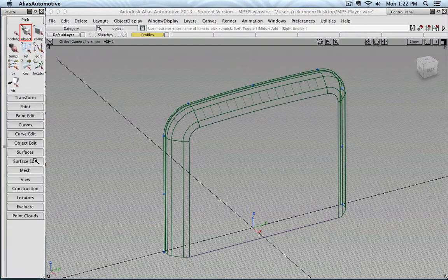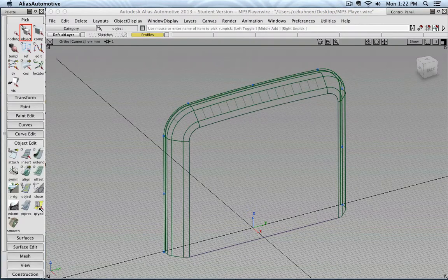And of course, again, if you would like to change those values later, you can always go to the query edit, click on the fillet, and then it jumps back to the fillet command. You can click on the small icon. So the radius input is selected, and then let's maybe see what 3 is going to do.